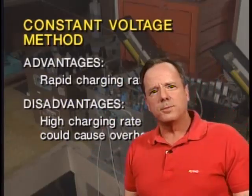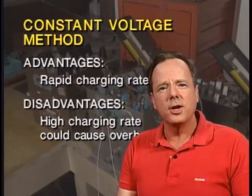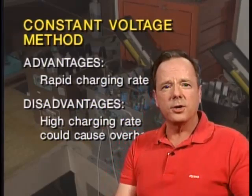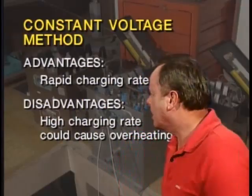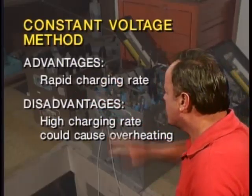Now the constant voltage method is what you're using in the air because a generator puts out a constant voltage, and what happens is the rate of charge is very rapid when the battery is very discharged, and the rate changes and gets less as the battery becomes charged. So the constant voltage method gives you a constant voltage, but the current or the rate of charging varies.